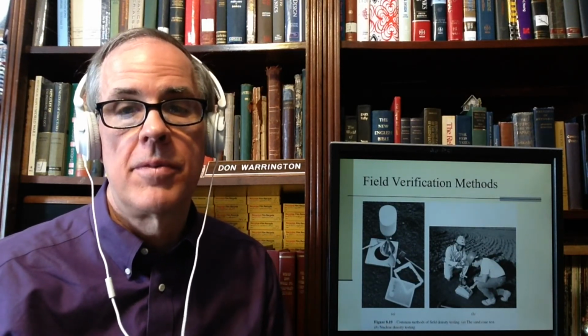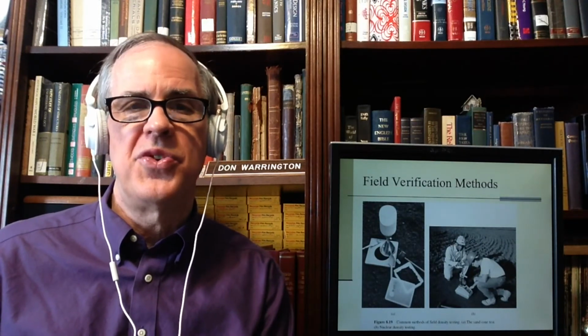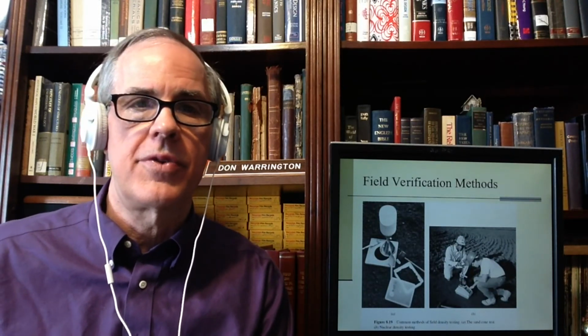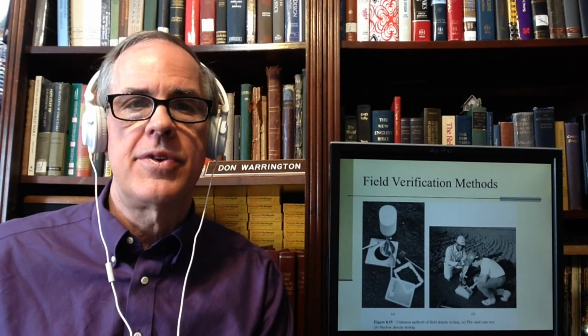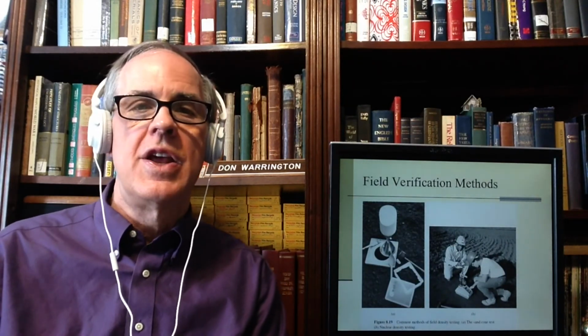That's the sand cone. It's a little time consuming, but there are some soils that still don't do well with nuclear density. So the sand cone is not completely out, and it's also another way of illustrating unit weight concepts in soil mechanics.